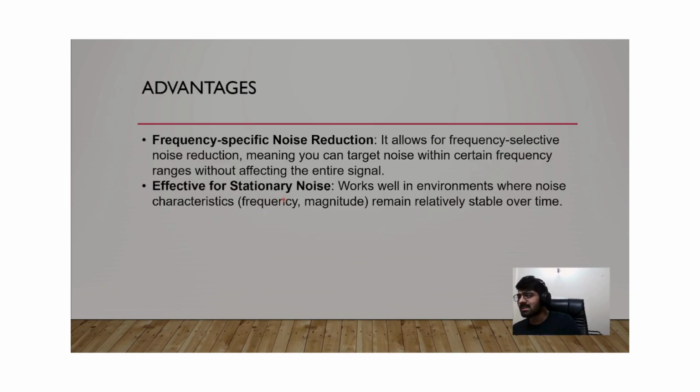Some advantages of DFT are that it allows for frequency selective noise reduction. Like we can have a specific range of frequency in which noise is present, and we can filter it out without affecting our entire signal. Then, it is effective for stationary noise. It works well in environments where noise characteristics remain relatively stable over time.